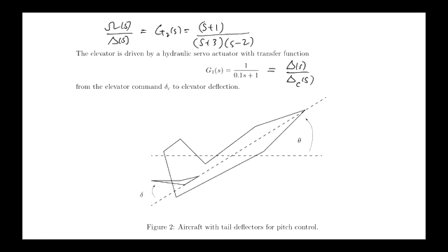All right? So the pilot doesn't control the aircraft directly. And the control surface here is this one here. Changing the angle of this control surface allows you to affect the pitch angle, right? And in particular, it allows you to affect the pitch rate, all right? And the pilot would struggle to do that directly, because to control an unstable system, you have to be really fast. Okay? And so there's typically a control system in place. And the pilot provides the reference for that control system.